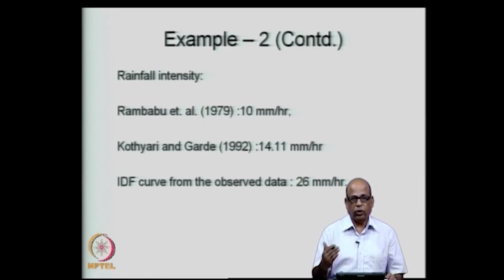for the next 30 years, 40 years, etc., you must have a mechanism or a method by which you are able to assess whether your IDF relationships can be held constant or they need to be changed as time progresses, and therefore use certain correcting factors in the hydrologic designs. This is especially true in the current context of climate change, where the relationships are known to be non-stationary now. There is a significant non-stationarity that has been introduced because of climate change, and therefore, the IDF relationships cannot be